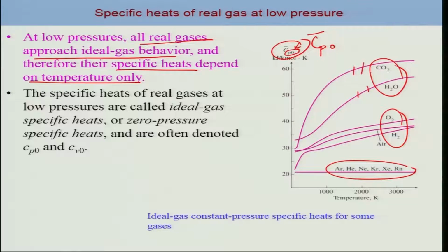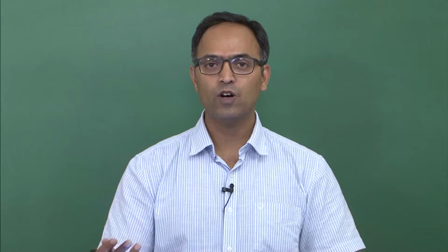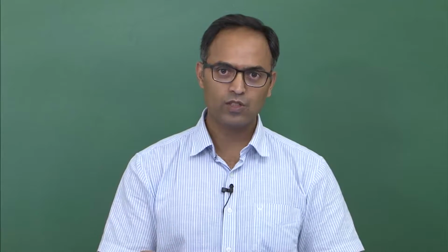So we can approximate different ranges and consider this to be linear within that. This behavior can be fitted to analytical expressions. For example, you can fit this into a cubic form or third order polynomial, and this is something we are going to make use of, because at the end we have to use it in order to find changes in the internal energy or enthalpy.